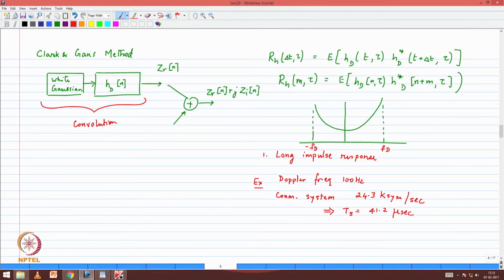And as you are familiar with from the computer implementation, most of the time our receivers will do 8x oversampling. So my sampling period, T sampling, is T symbol divided by 8, because I'm doing 8 samples per symbol, and 1 by T sampling is F sampling. That's my sampling frequency. That corresponds to 194,400 hertz.